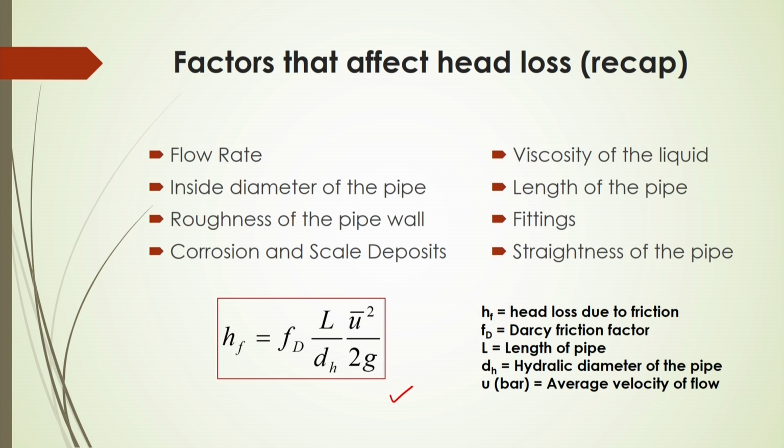If we increase the velocity, this frictional loss will increase, and in that case some other factor like viscosity is very important here. The viscosity effect will be considered in this by F d. This Darcy-Weisbach friction factor depends on the Reynolds number, where this Reynolds number is a function of viscosity of the fluid. So, from this we can have the effect of viscosity on this head loss.